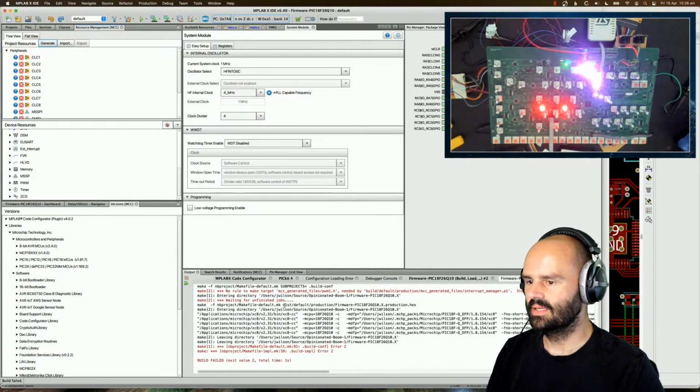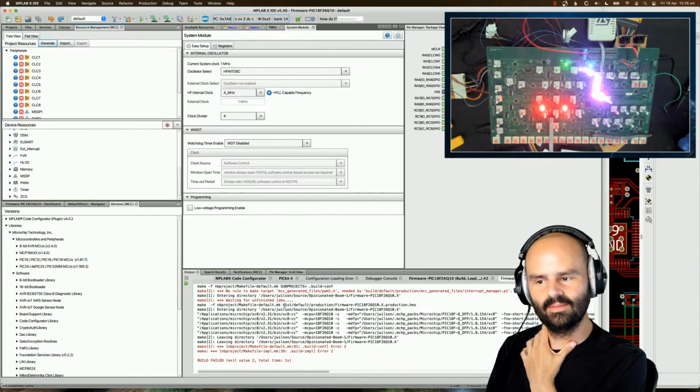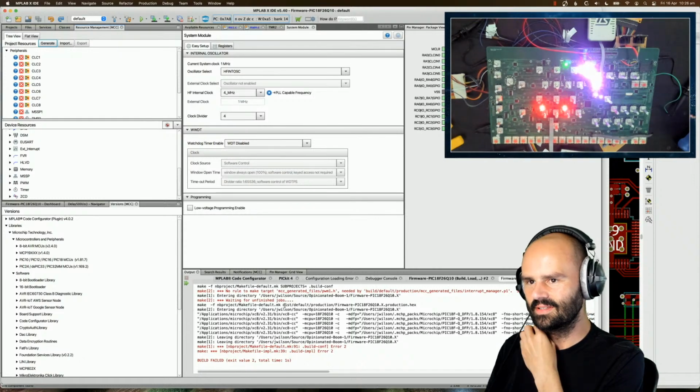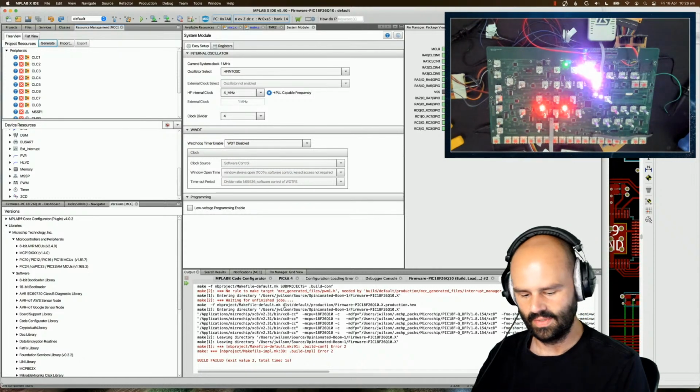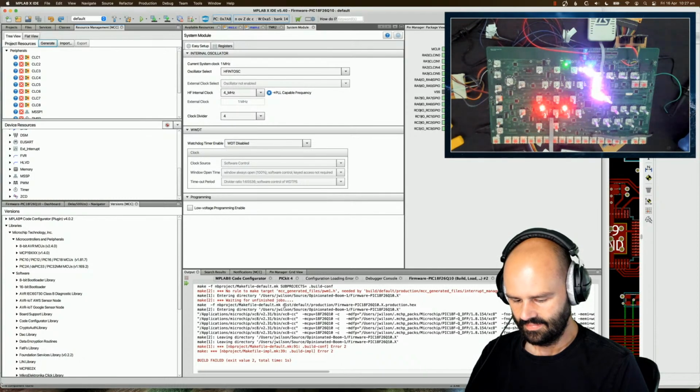The PIC we're using here is a PIC18F26Q10, chosen for the fact that it was readily available at the moment in the chip shortage, and it has all 8 CLCs on there for handling 4 rotary encoders. That was basically the main thing I needed it for. It's just annoying.